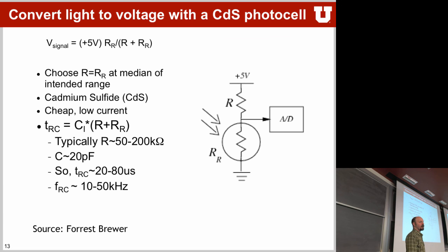Now there are a couple of problems coming up. First, in a voltage divider, if you are an EE, you should know that as soon as you hook up something to this voltage over here, you change the equations. So you want to buffer it before you start measuring the voltage itself. You can have just a unit buffer on there, which we'll cover in a second for everybody who doesn't know what this is for. So you want to buffer whatever is on here in order to not change the voltage divider.